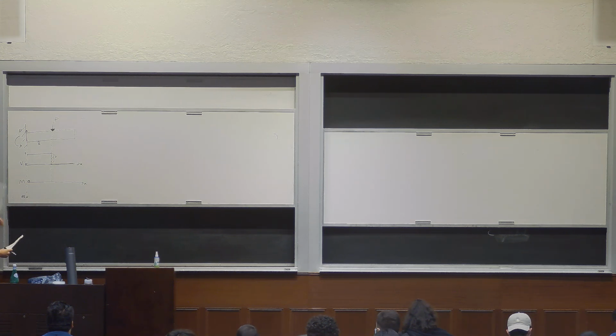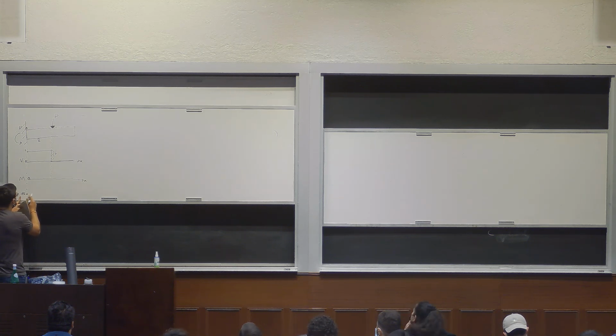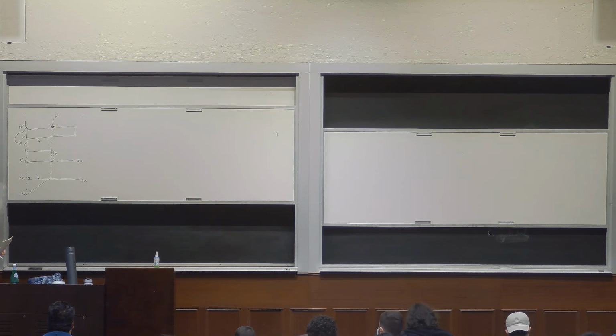That's the magnitude of this moment, right? And like I said, this constant value that you see here is telling you that the slope of this is constant, okay? So the slope is going to be P. And if this is PL, then it's going to go down to 0 at a distance L, okay? And then at this point it is 0, okay? So this is a very simple example of these shear moment diagrams.